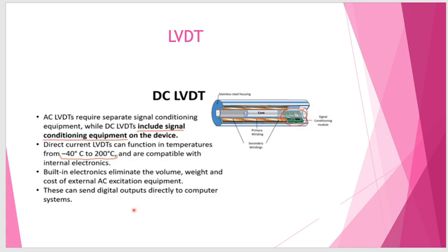Now let's talk about some disadvantages. First of all, there is an inductive issue. This type of transducer is sensitive to magnetic fields. Here the magnetic field spreads out, so it affects the performance. That's a downside. The primary transducer will convert the quantity into displacement. Then using a secondary transducer like an LVDT, we can turn this displacement into an electrical voltage signal. Finally, the last topic is applications, where it is used in industry.